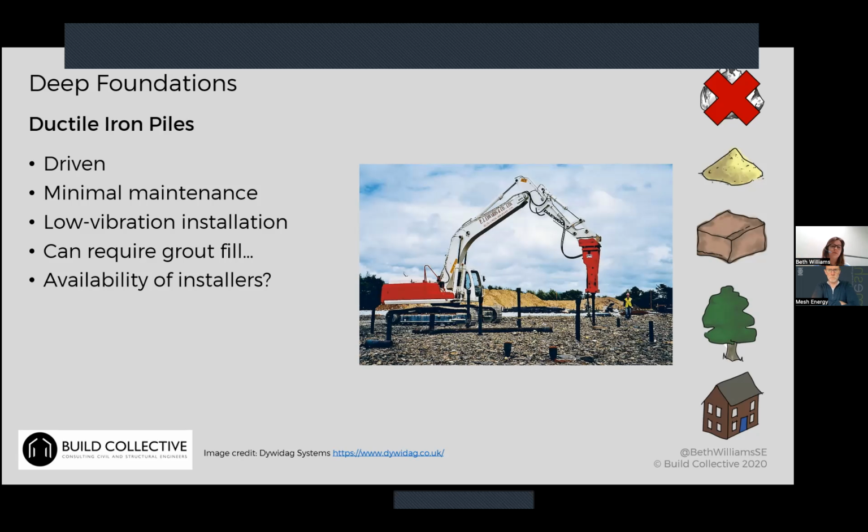There aren't a lot of installers for them, so getting availability and a good price on somebody who can install them is a little bit tricky sometimes. But they're a good mini pile option. They've got a really long design life. From a design perspective, they're a bit more flexible than a screw pile, particularly because you can get decent lengths on them, 25, 30 meters if you need to. So yeah, there's an option there as a longer length pile.